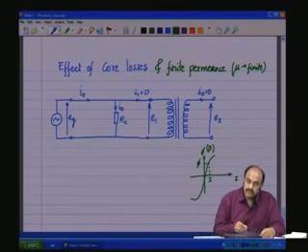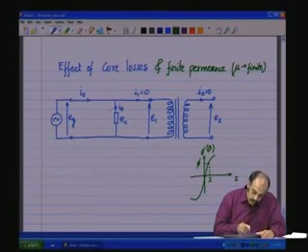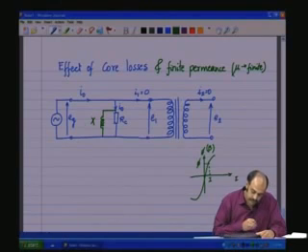And I1 should still continue to be 0 because this ideal transformer is not going to take any current to set up the flux. So from here I am going to have one more component, and let us call that one XM.